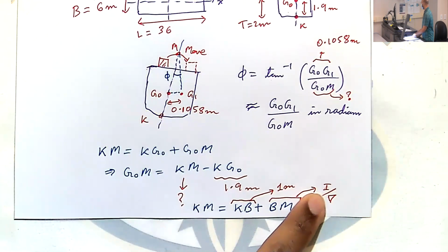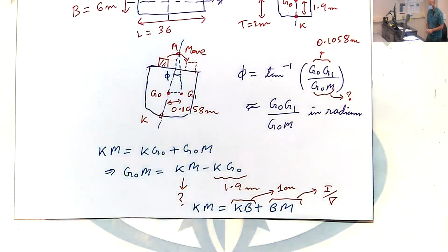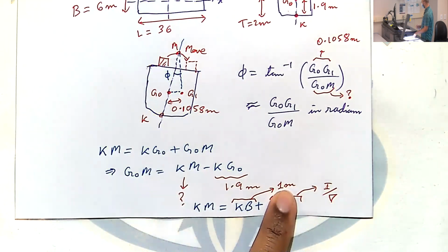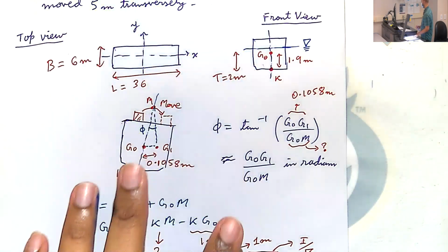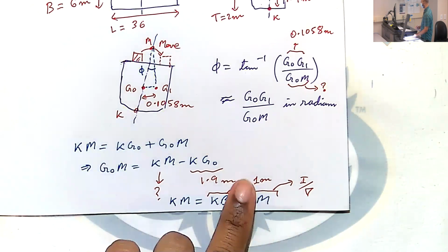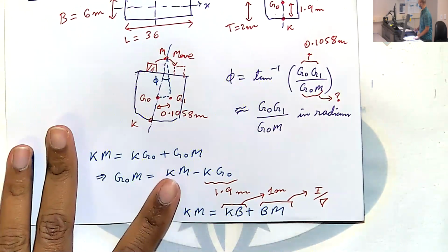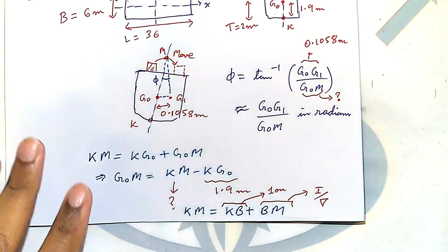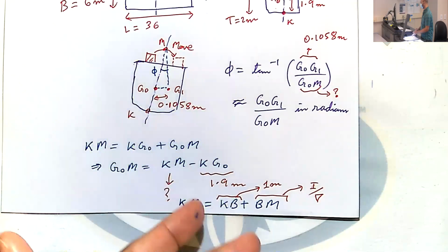You know how to compute the I, you know how to compute the nabla, so you have everything you need to compute phi. Is everybody good on KB equal to 1 meter? Only if this is a perfectly rectangular cross section; otherwise not true. It's half of the draft. Yes, that makes sense. Any questions? There's not much to do here, you basically just have to crunch numbers.